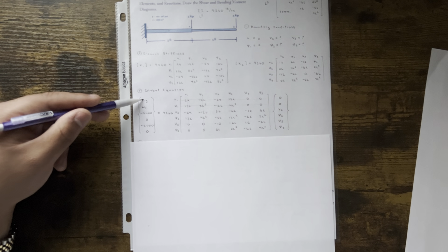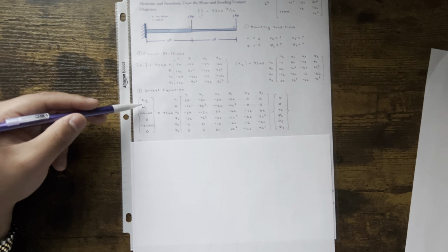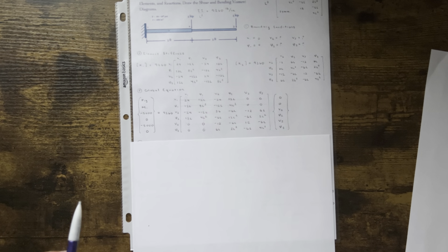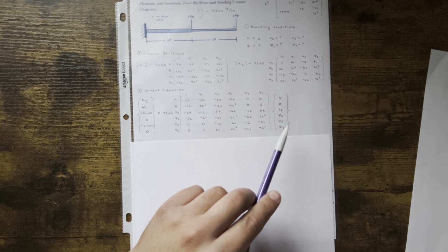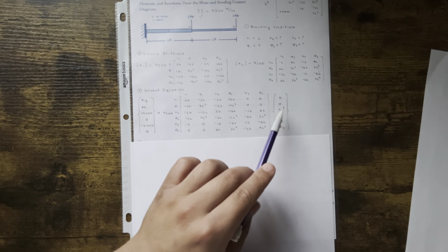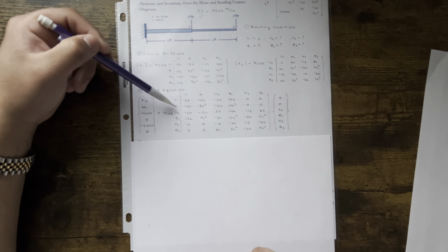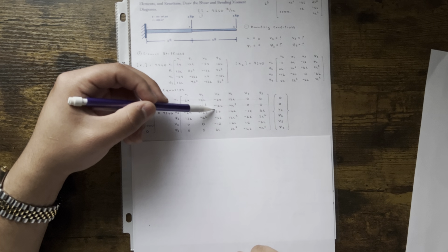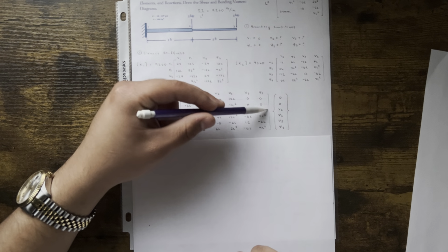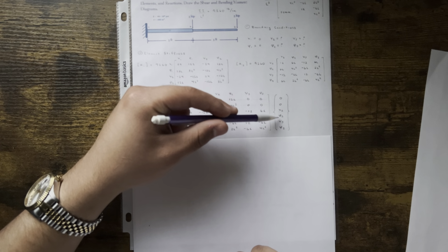Now you could solve it, right? You have, in this case, 6 equations, 6 unknowns. 1, 2, 3, 4, 5, 6 equations. And then your unknowns are F1y, M1, V2, Phi2, V3, Phi3. Now, before you do that, you want to start crossing them out. In this case, we know they're zeros. So when V1 and Phi1 are 0, we cross out V1, Phi1 in the x direction, left to right. So that means we're left with this matrix right here, a 4x4. And we're going to solve for V2, Phi2, V3, Phi3.